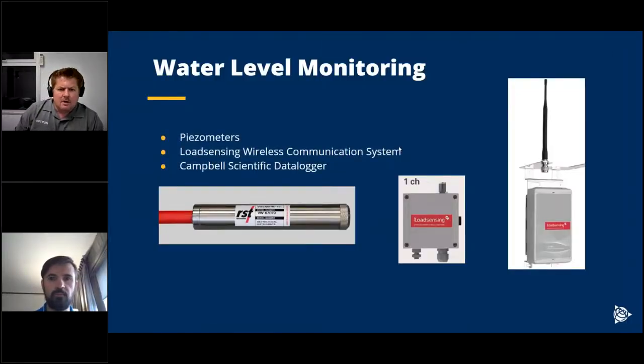Then for the water level monitoring, we actually use piezometers in both dams. I think one piezometer is from RST and the other one is from Geocons. We don't really have a preference as to which brand we use. For one piezometer, we use a load sensing wireless data logger and the load sensing gateway. And for the one at the lower dam, that is actually connected to a Campbell Scientific data logger. So we use various options as well.